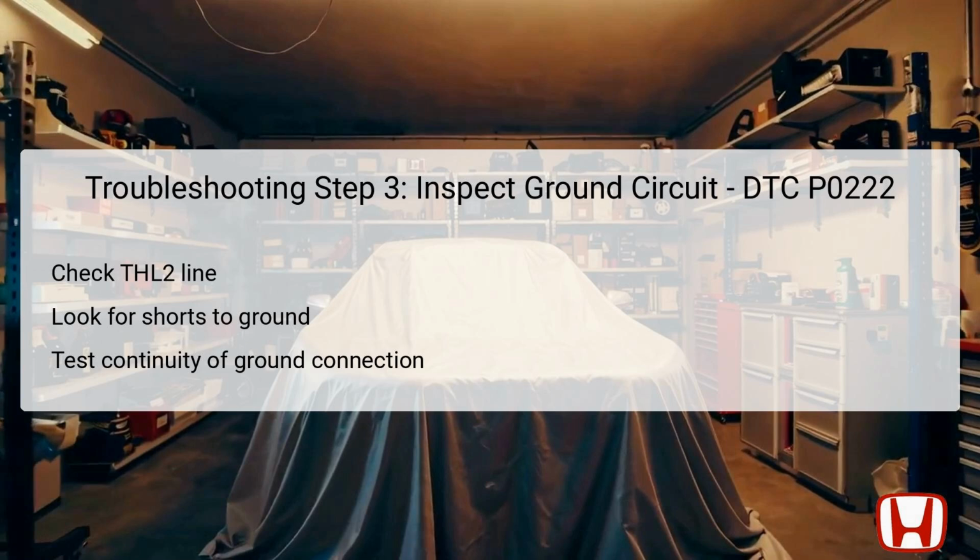Conducting this examination ensures that the sensor has a reliable reference point for voltage, allowing it to function correctly, thereby reducing the likelihood of returning to the DTC P0222 status.